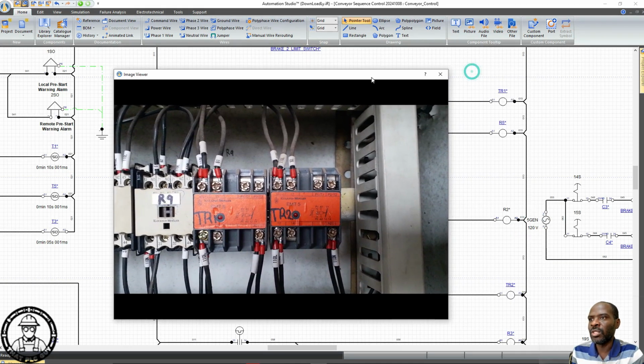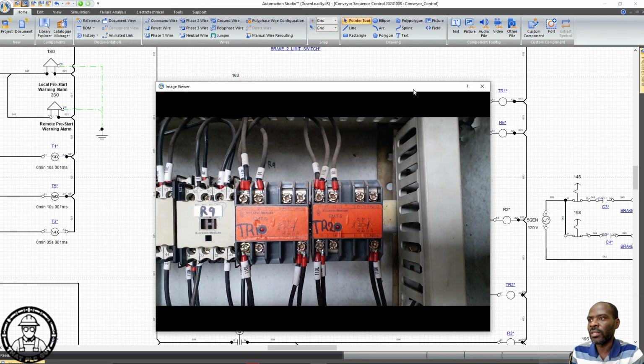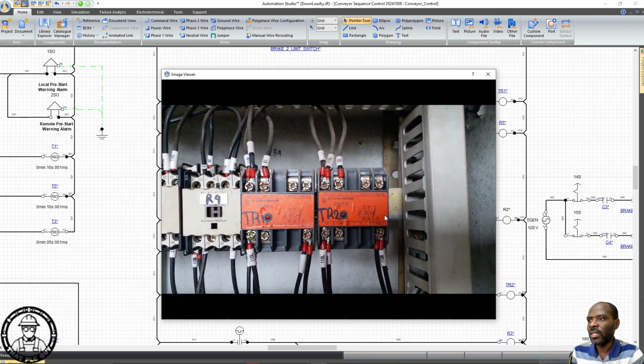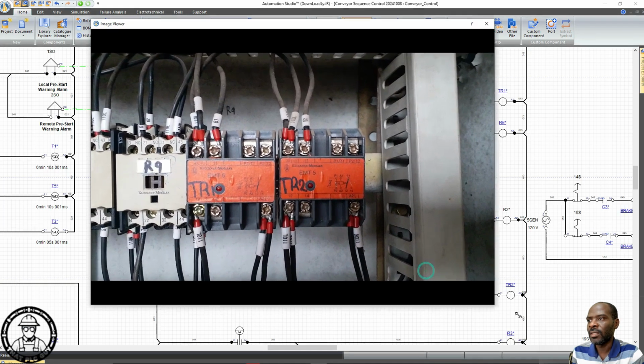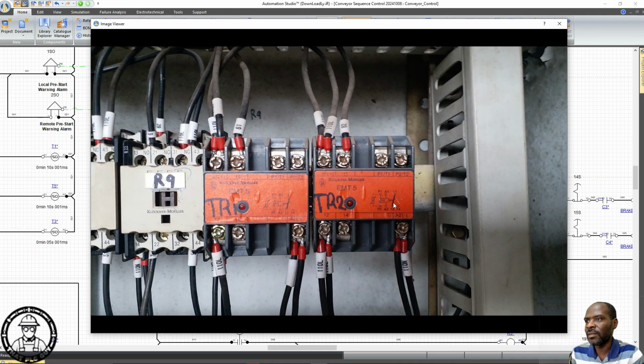And when we talk about the coil, according to this schematic, you'd notice that based on this description the coil is actually across A1 and A2, right? So wherever you find A1 and A2, that's the coil for the device responsible for monitoring what the motor 1 or motor 2 temperature is, right?